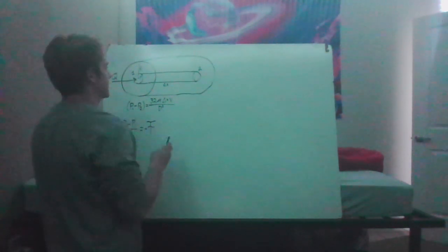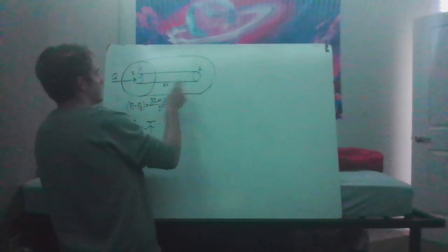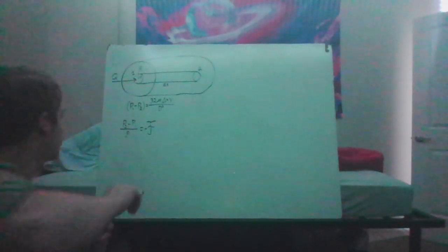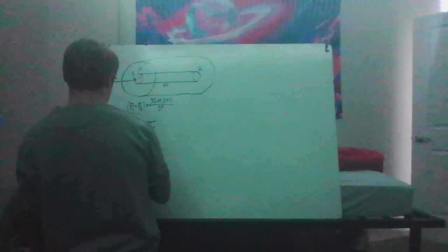There. And we will not have the vertical or kinetic energy heads because, again, there's no geometric change between point 1 and 2. And then we have a horizontal cylinder. So that's why we don't have the vertical head as well. So now, as you can see, this is oriented P2 minus P1. So we can actually flip that and make it P1 minus P2. And that will just make this positive.